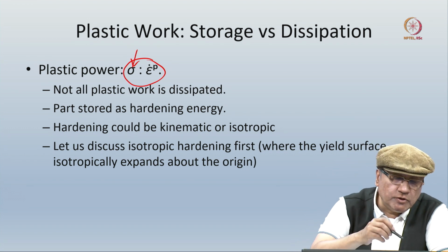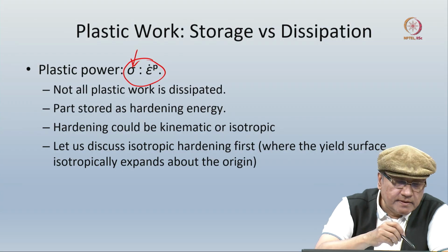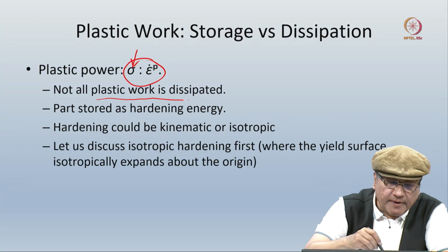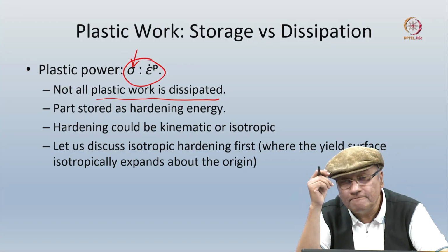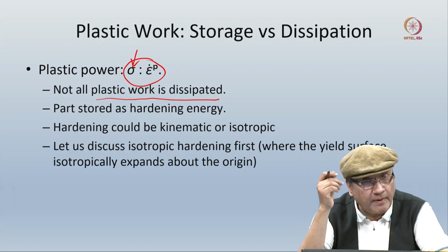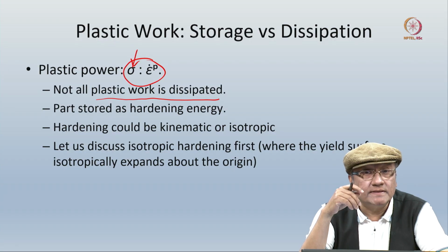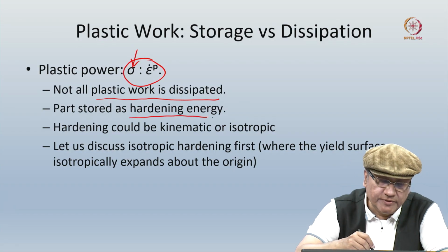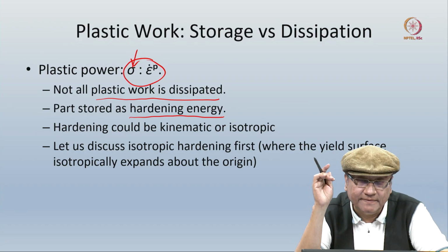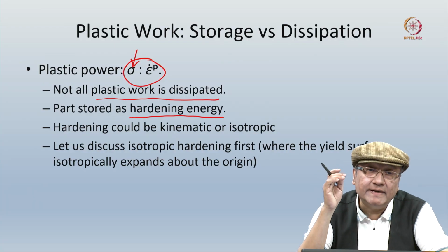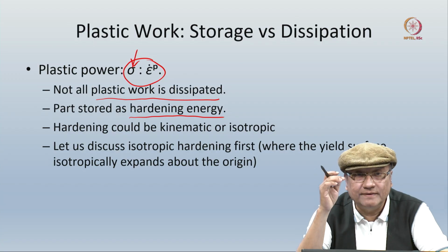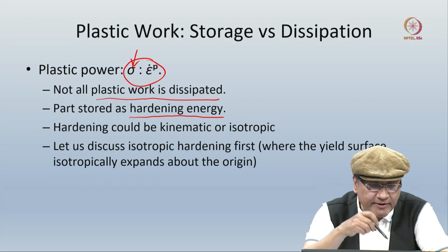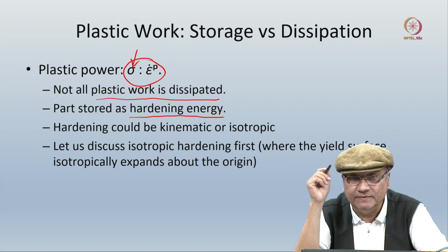But even though this is the plastic power, not all of this plastic power really is dissipated into heating finally, okay. Part of that can be stored as the hardening energy, which is never manifested in heating. But that does not mean that by removing the loading you really recover this hardening energy.